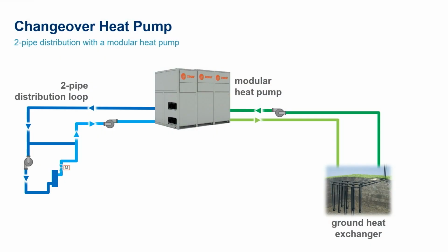With that understanding of two-pipe changeover systems, let's look at some units in geothermal systems. First up is a modular reversible heat pump. The assembled bank of modules operate in either cooling or heating mode of operation. All modules are in the same mode of operation and change over together. Operationally, these units reverse the direction of the refrigerant within the unit by a 4-way reversing valve.